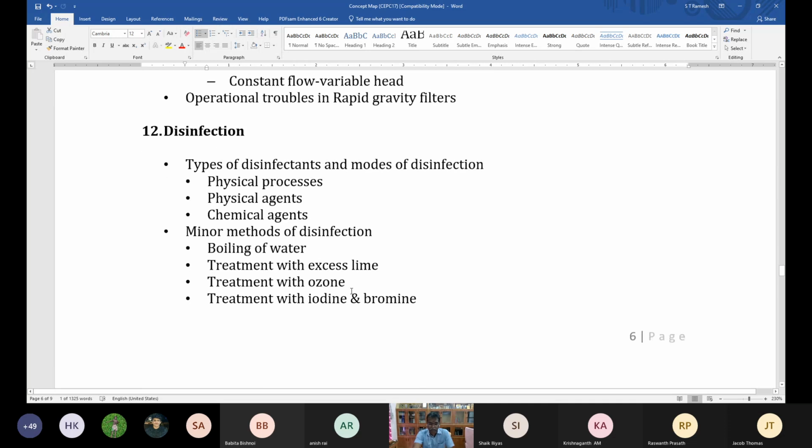Okay, and the last part is about disinfection. All the treatment systems we discussed prior will not attempt to remove your microbial population. That is important. That's what people used to say: tap water from a source, have a treatment at your household level or point-of-use technologies, and after POU also just have a simple boiling. Make sure that there are no pathogens or microbial contaminants in the water.